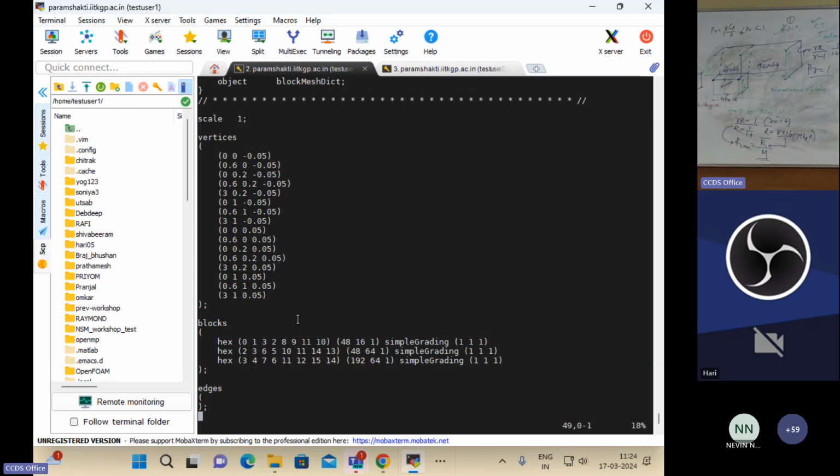So you can appreciate that even if the geometry is a little bit more complicated than the previous one, we have to take care with multiple blocks. If you want to solve a very complex problem, blockMesh is not advisable. You can use the fluentMeshToFoam command to convert the ICEM mesh to a Fluent, OpenFOAM readable format.